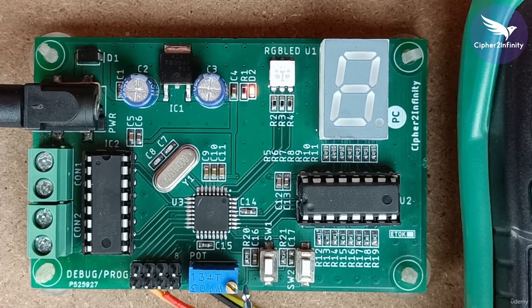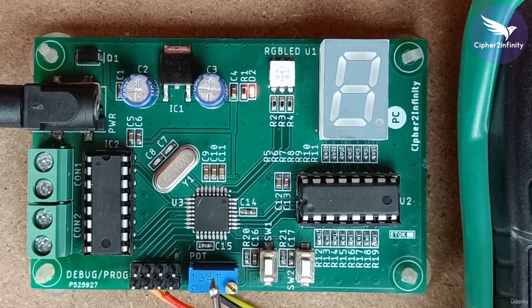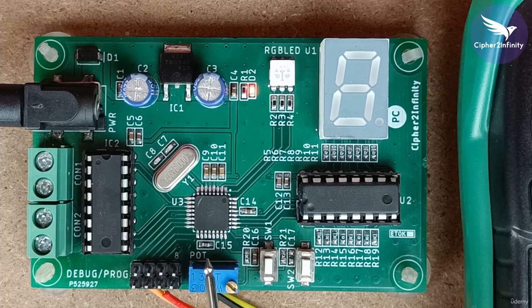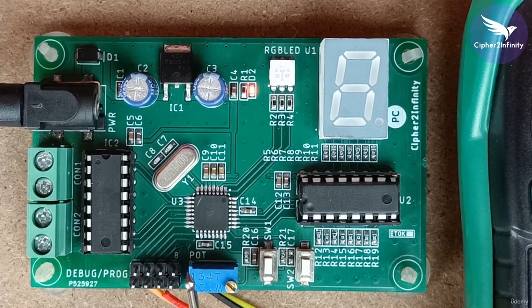And if the plus 5 volt is available, it means that there is a problem with this preset, and you will have to change it, because even after providing the supply to this preset, it's not generating the voltage on the center point. It means that there is a problem with this preset, and you will have to replace it. So that's how you have to do the testing and troubleshooting.